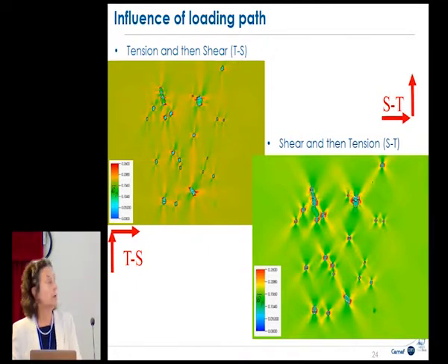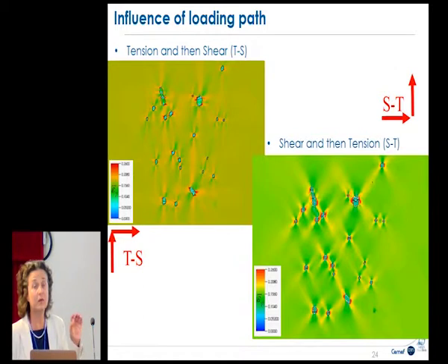Okay, so here we have an example of this mesh, a single mesh with just refining around different zones. Here we refine around a zone in which we need a geometrical adaptation, and we refine here because we know that in this zone there is, for example, localization of stress or strain, and it is very important to have a refined mesh here.